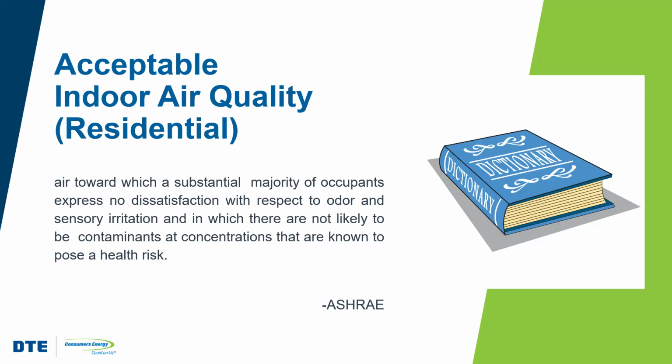We don't put that 80% in there. We just say that it's air with which the majority of the occupants would express no dissatisfaction. And we specifically call out certain things that may be important to those occupants. So we're specifically looking at odor. We're looking at sensory irritation, things that might cause respiratory issues.